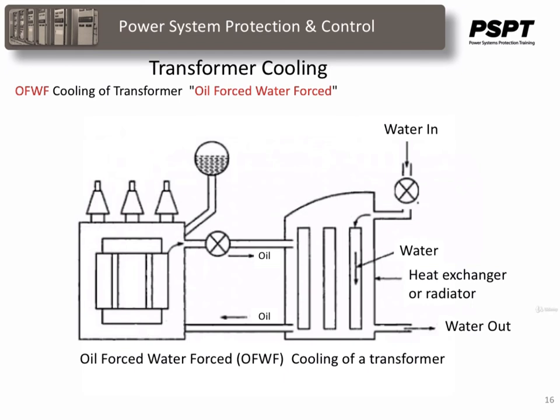The windings and the core are immersed in oil. A cooling radiator is mounted externally to the tank of the transformer through which the oil is pumped. Cold water is forced to circulate through the radiator. This water carries the heat away from the device. This design is usually implemented on transformers that are used in high voltage transmission lines. The biggest advantage of such design is to reduce the size of the tank. This reduces the cost by a huge amount.